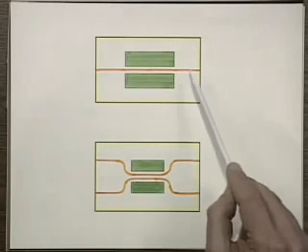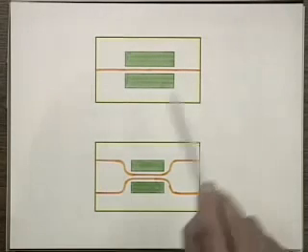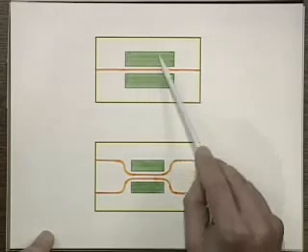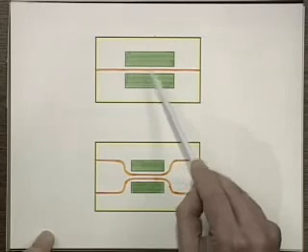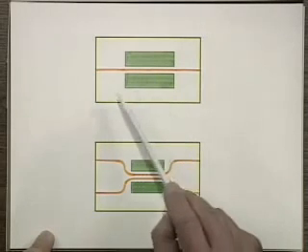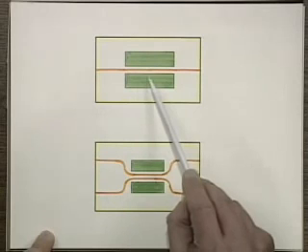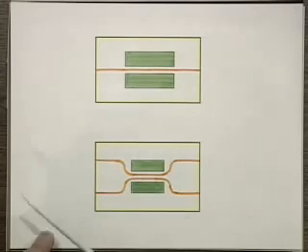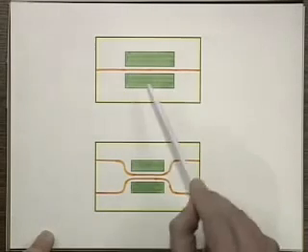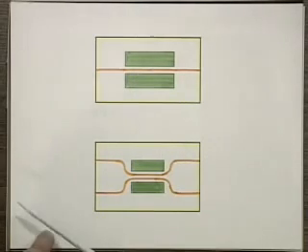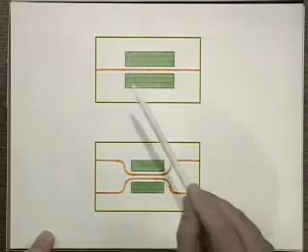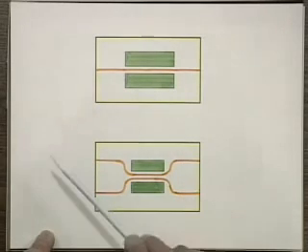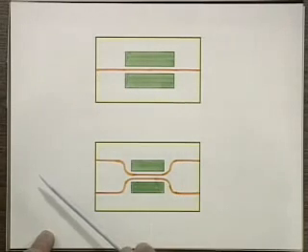All right. So now, how do you create a phase modulator here? If this material is, for example, slightly electro-optic, then by putting electrodes here and applying a voltage difference between them, you can change the index, either in the cladding or in the core, simply by applying a voltage. This way, you can phase modulate the light propagating in this section. You can do it pretty fast, so you can get very fast phase modulators. And if you ramp the phase using serrodyne techniques, you can also do frequency shifting quite easily using this device.